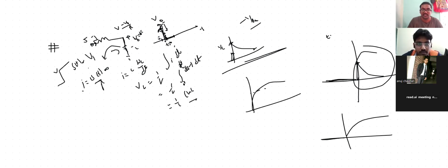Step response and the remaining are forced responses. We have two responses in a control system: natural response and forced response. Impulse is the natural response. Nothing is forcing, so we can analyze the system without any conditions or operating points also. That's why the impulse response is important, in the sense that it is the natural response of the system. We will get the exact behavior of the system.